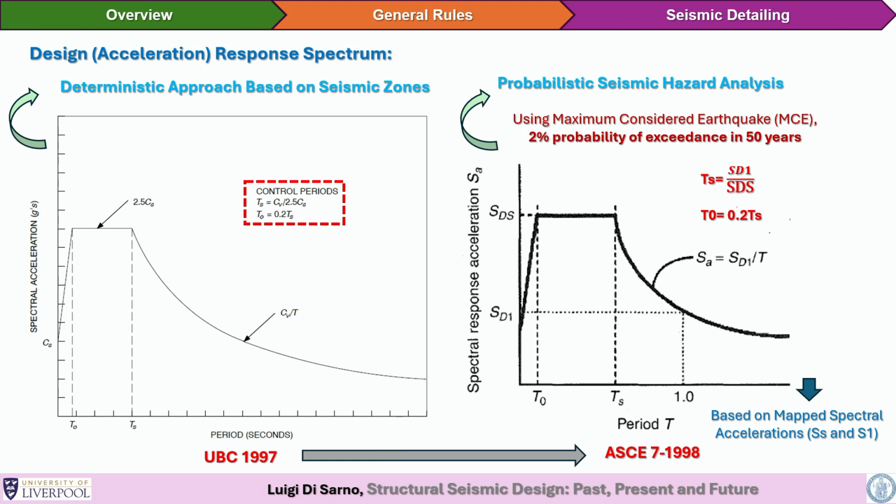Most often, and I come from experience in Europe, but also being exposed to a number of projects here in this part of the region, sometimes they are not well matched. So there is a match of the seismic details that will comply with the capacity design rule, but when you look at the input, it's not exactly the one that you should design for, or the one that is most suitable for the type of structure that you are designing. A hospital, for example, or a critical facility like a power plant or refinery and so on.